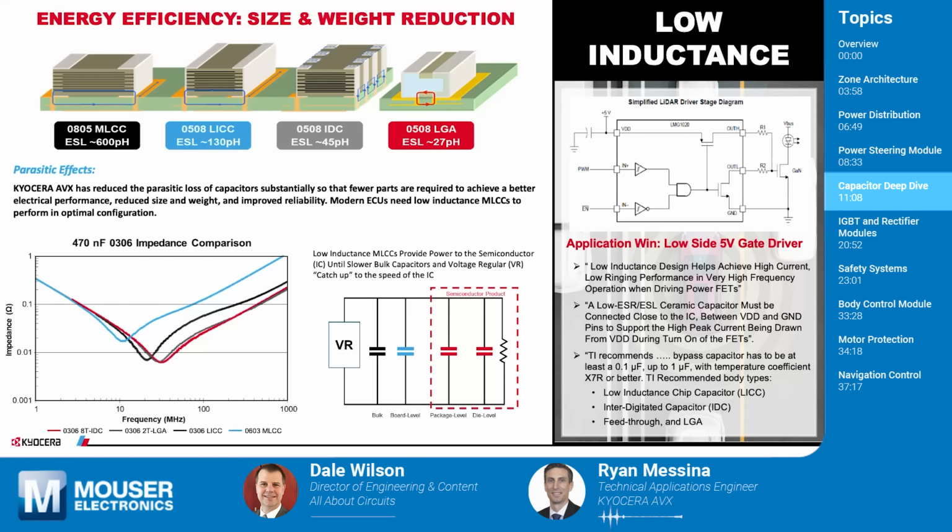just based on the geometry of the part. These are especially applicable when you're talking about having all of these ECUs right at the zones. So high frequency decoupling is going to be a very basic need that you need to fulfill in the zonal architectural layout, due to the increased communication speeds, higher processing speeds with the ECU, and overall increased power load magnitudes.